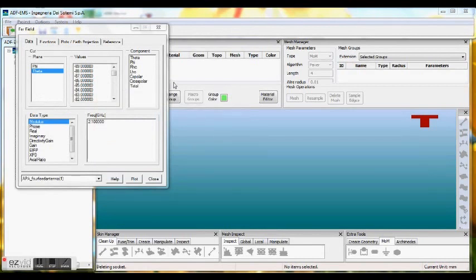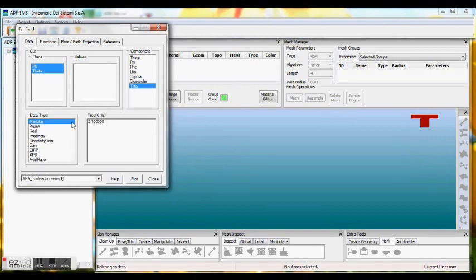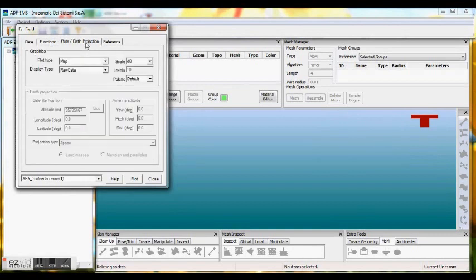In this section we will consider both phi and theta, and we'll click on this as total, and we have already defined our cutoff frequency, and we need to do some small changes. So just come to plots and path projection, click on maps to waterfall, and I'll go with linear. Just click on plot.